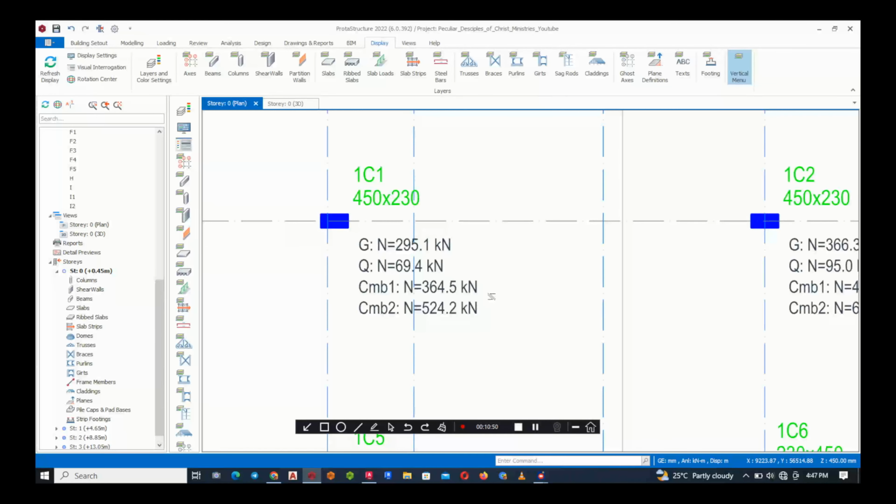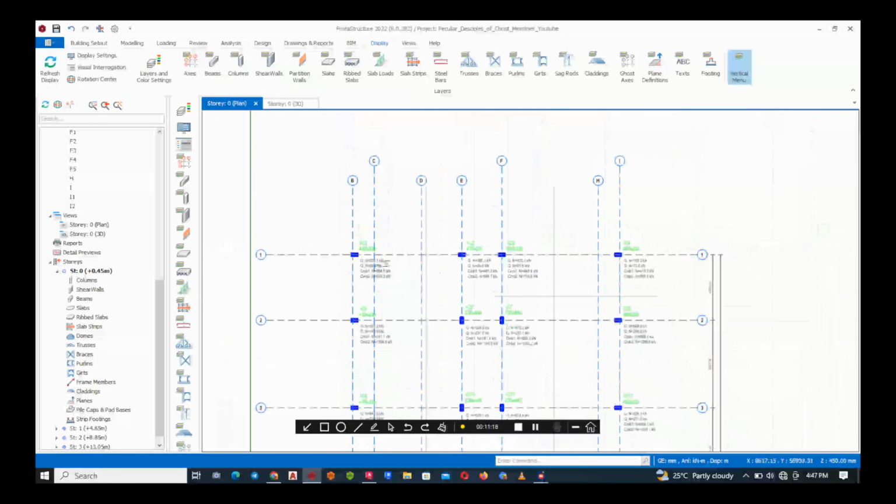It is because during the soil test, they have already used some amount of factor of safety. So if we now use another ultimate load to design the pad footing geometry again, that is the size of our pad footing, it will be a very wasteful design. So that is why we use service load for our pad footing sizes. Okay, now let's move on.